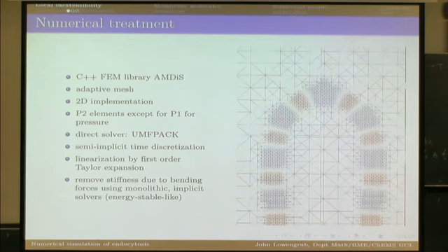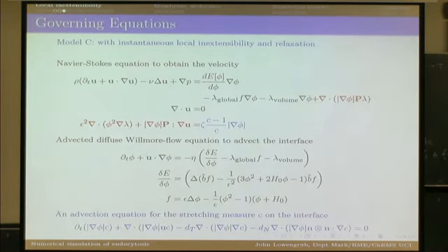And so one of the key things is removing the stiffness. So where does the stiffness come from? The stiffness comes from this piece, because this involves fourth derivatives, right? And so this causes the stiffness. Basically, you would have to have the time step less than the space step to the fourth power, so that's very restrictive. And it's not easy to do because this is coupled with this only through the fluid.